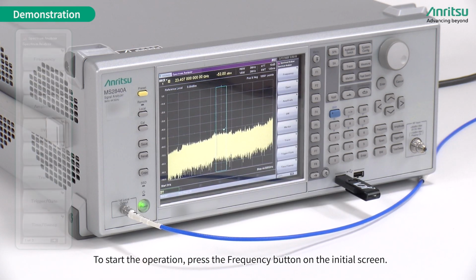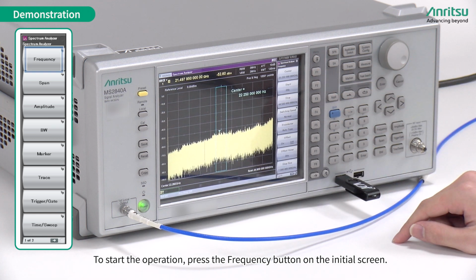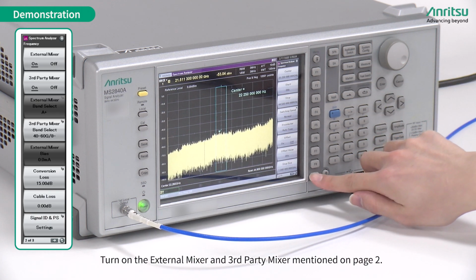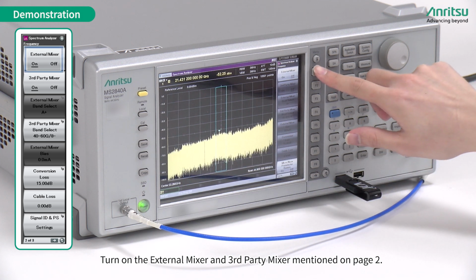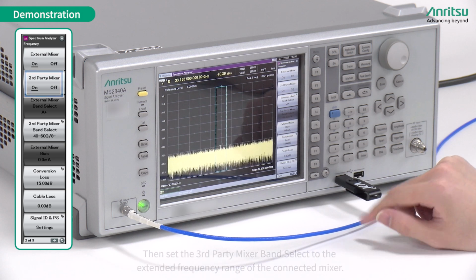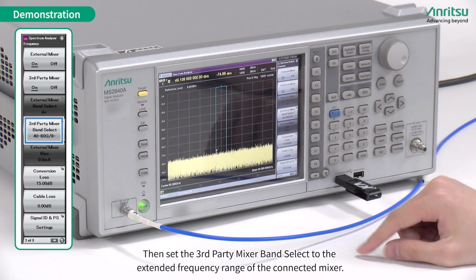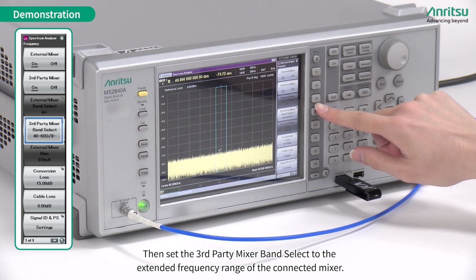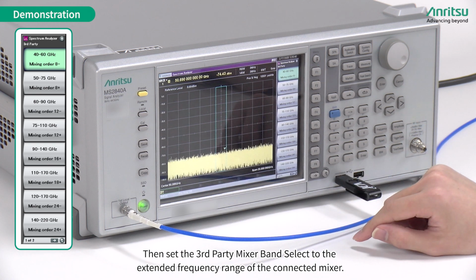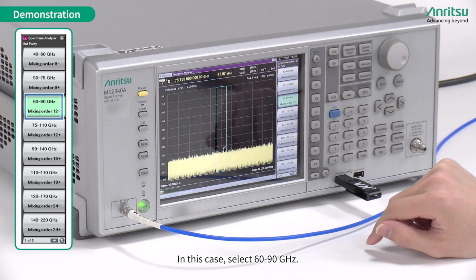To start the operation, press the frequency button on the initial screen. Turn on the external mixer and third-party mixer mentioned on page 2. Then set the third-party mixer band select to the extended frequency range of the connected mixer. In this case, select 60 to 90 GHz.